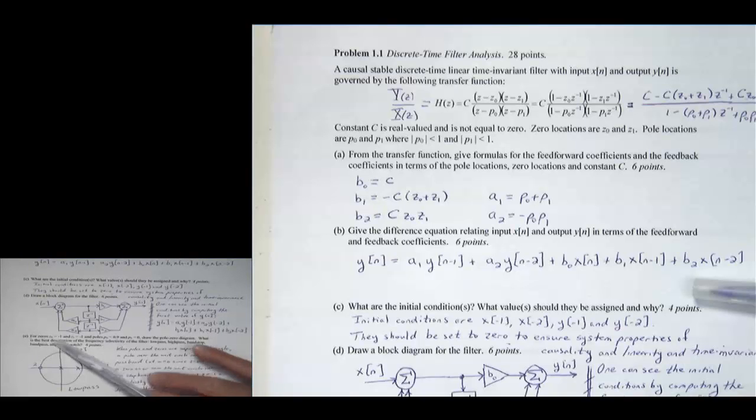And I think a few people interpreted this as -1 and 1. I think that was probably just speed, stress. That does change the answer quite a bit. If it's -1 and 1, I get a notch and a low pass filter combined. It's weird. It's kind of a weird combination. All right, but the intent here was a low pass filter.